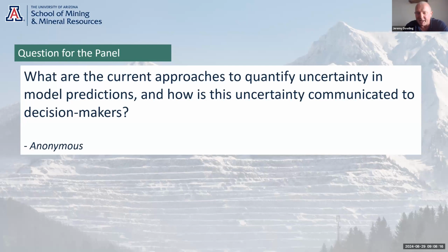So that's the kind of classic uncertainty analysis that's thought about with groundwater models. But 8 times out of 10, that uncertainty is irrelevant for pore pressures compared to things like the operational implementation of the dewatering system that was assumed in the predictions, right?